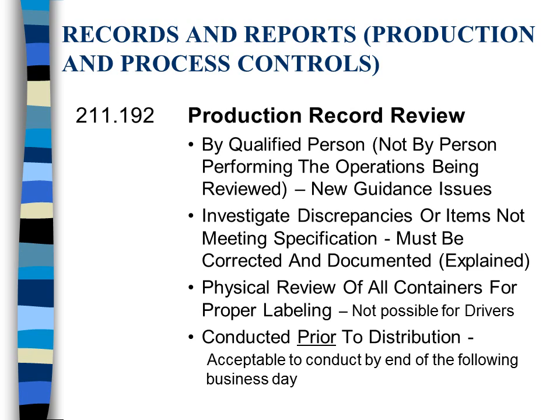Our guideline for liquid oxygen is 99.5 or greater. If you show something that is less than 99.5 or greater than 100.0, that is an out of spec. You must contact your QCU member and let your QCU member direct you in the next steps.